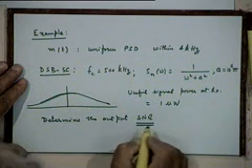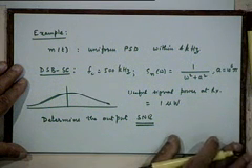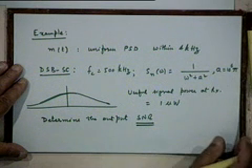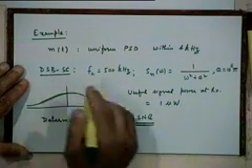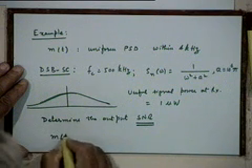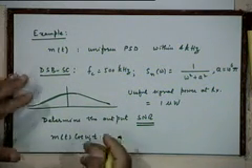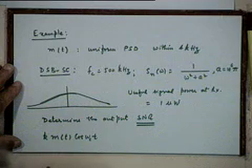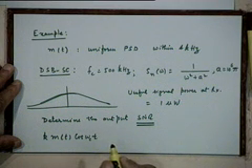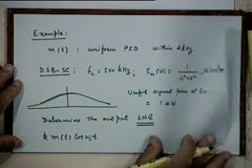Of the receiver. So how will we do that? We are transmitting the DSBSC signal, which is m(t) cosine omega_c t. It will get attenuated by some scaling factor. Let's say the received signal is k m(t) cosine omega_c t. So what will be the demodulator input now?